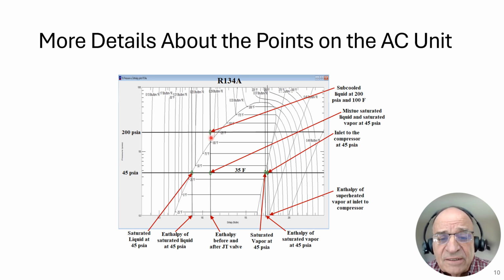So now looking at this, you got the same thing, a temperature drop, which is caused by the pressure drop. And this is 100% liquid, but this is liquid and vapor. Where are the liquid properties? Liquid properties are over here. Where are the vapor properties? The vapor properties are over here. And you can look at on the chart as well as by way of table. You can do in tabular form, which is more accurate.